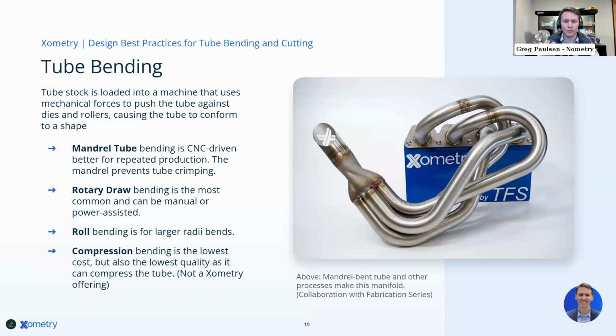And if you're living in a traditional fabrication world, you may be thinking about tube in a series of straights, elbows, and J's in your design, and you're buying basically stock components of these straights, these elbows, and these J's, and then stitching them together. So this feature right here would be a straight, weld, elbow, weld, straight, weld, elbow, weld, straight, weld, elbow, weld.